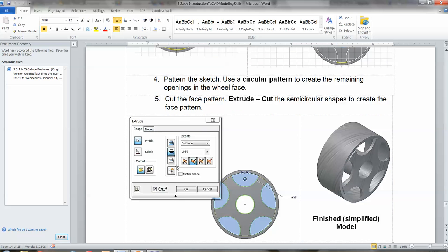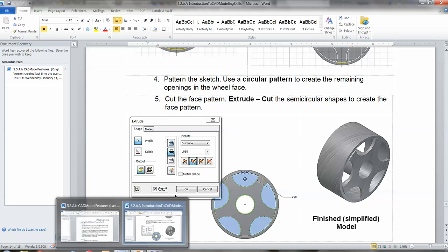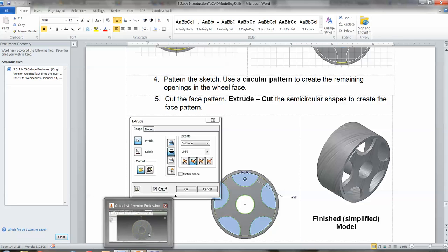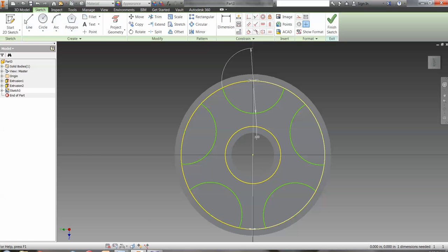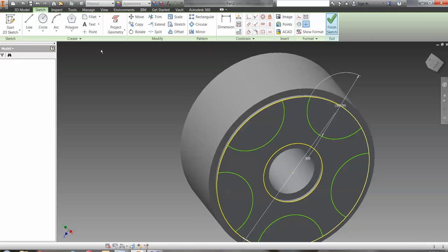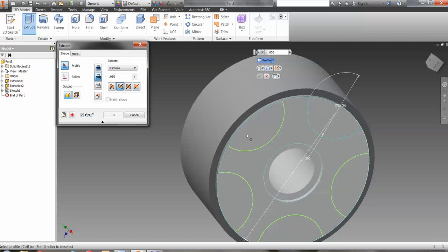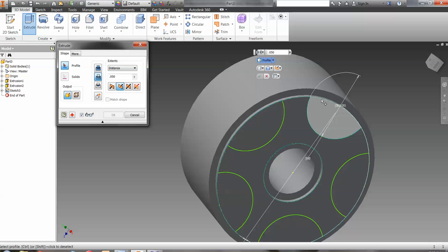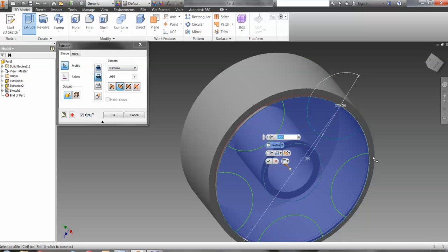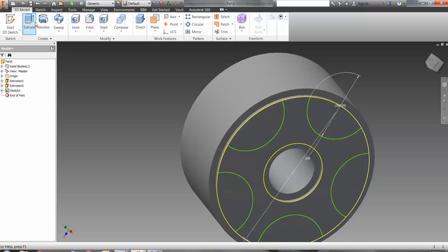We're going to do an extrusion cut. We saw this once before with the star, if you had to do that. If not, you're lucky, but now you get to do it. So I'm going to go finish sketch, go to extrusion. This is going to be a cut, so we're going to select cut, and then we want to make sure that we're going through and we're selecting all of just those little bits. So, whoops, we got something extra there. Let's try that again. We're going to cancel that and we'll try it again.